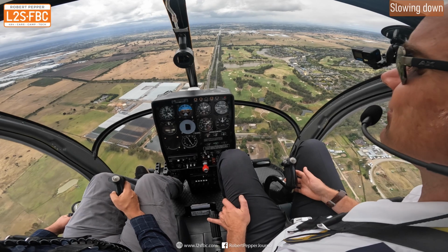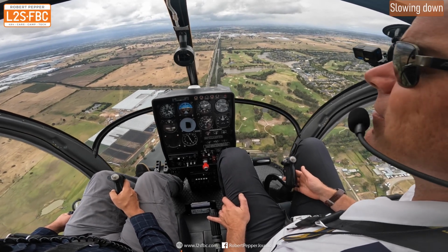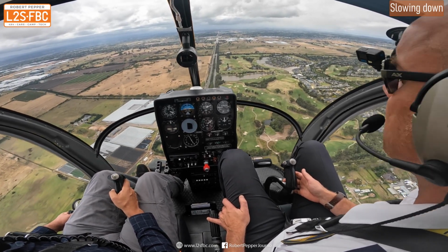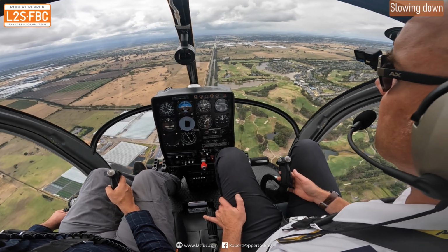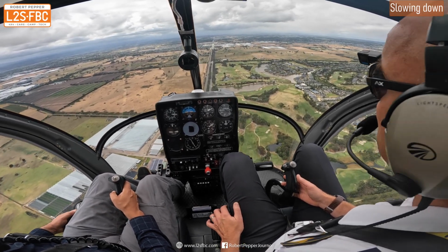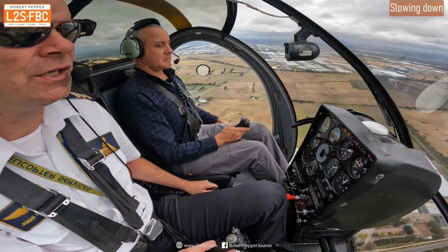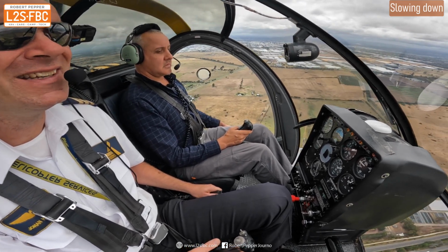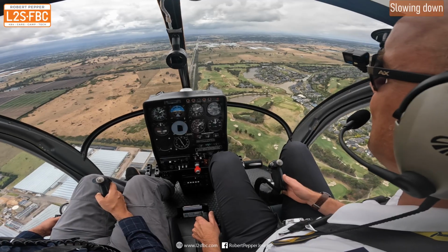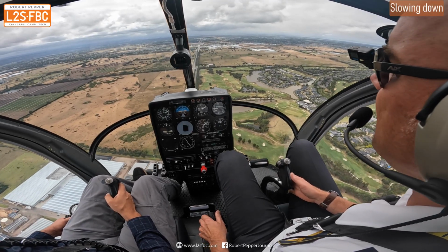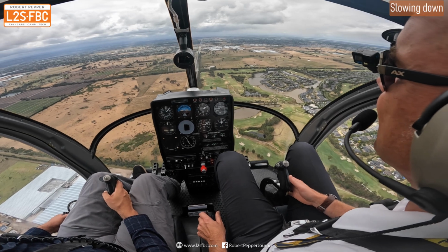And also as we slow down, the helicopter starts basically flying within its own downdraft, and that means the rotor blades aren't as efficient, so I'm going to need to increase the collective a bit once I start to slow down, and it's all just one thing changes another thing, but it's pretty cool just to bring the aircraft back and then be, well, pretty much almost come to a hover, as you'll see.